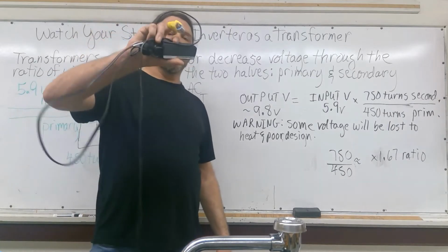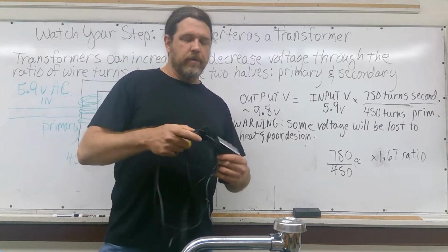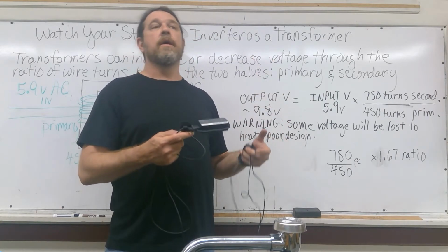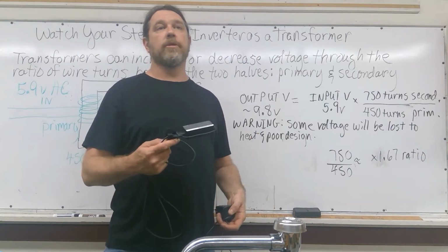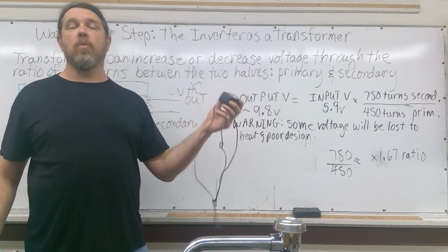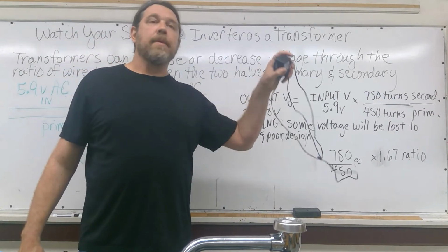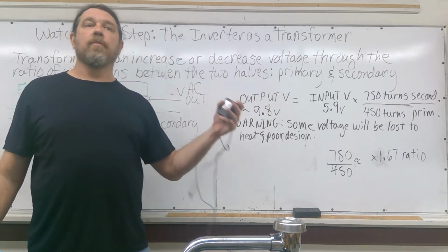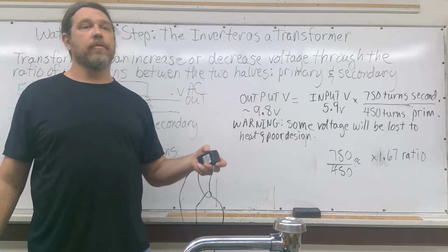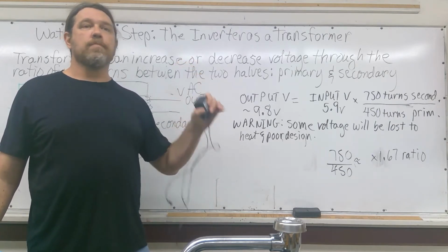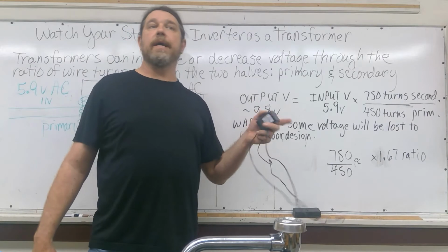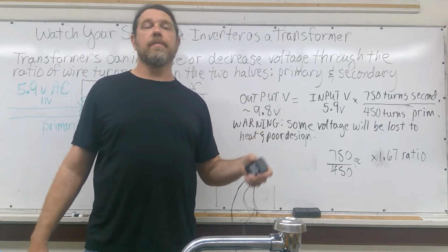Your laptop or computer tends to have a supplementary transformer that steps voltage down, because computers operate on much lower voltages than the 120 that comes out of your wall. And of course, everybody's seen these wall warts that also are dropping down voltages considerably from the 120 household to 9, 12, 5, 3.3, which a lot of small devices tend to use. Sometimes they are also turning it from AC to DC, and other times they're just keeping it at AC.